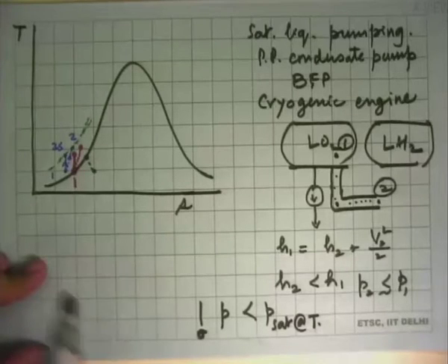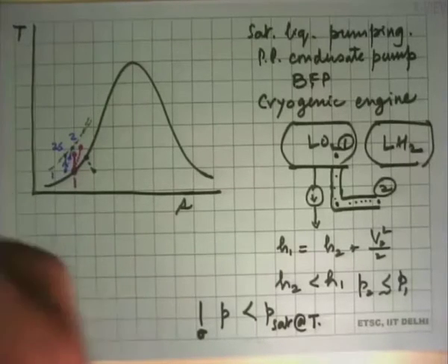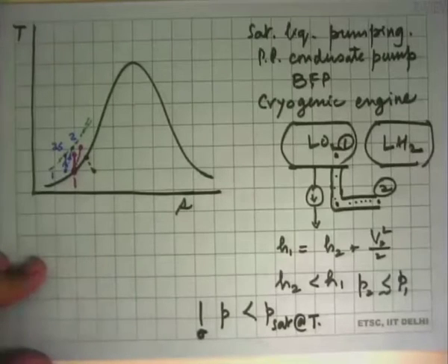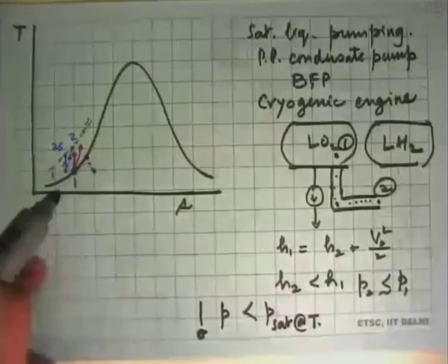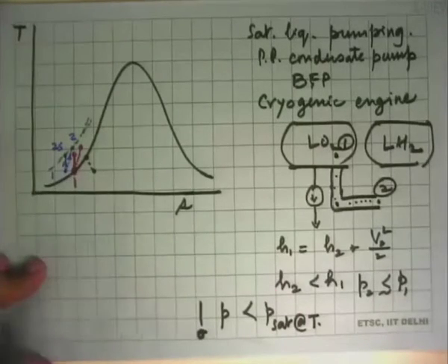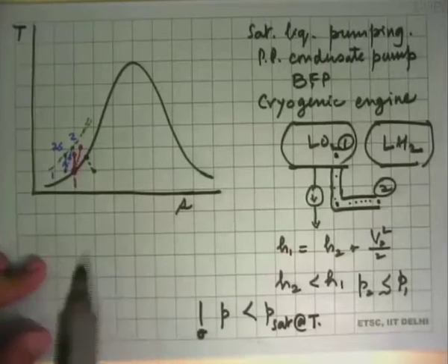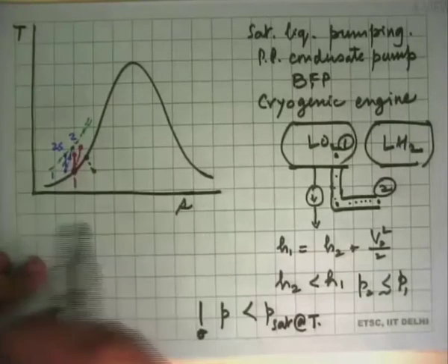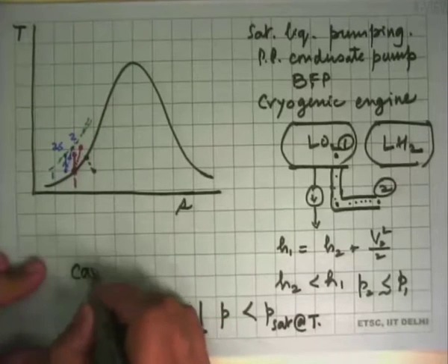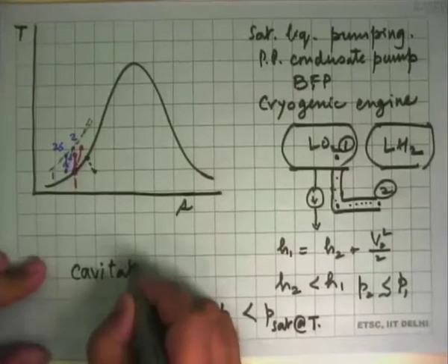The moment this vapor bubble moves out into a zone where the pressure is more, it will collapse suddenly and give out a shock wave, and that's why you will see that some pumps sometimes make a hammering sound, as if something is being hit inside. There's nothing hitting it, just that vapor is being formed, and this is called the issue of cavitation.